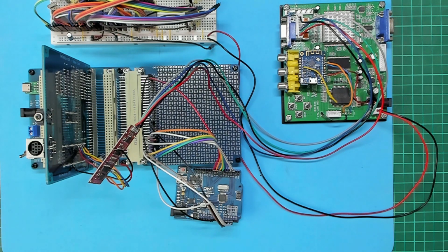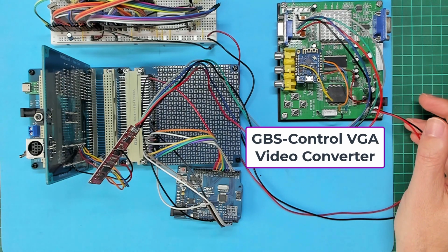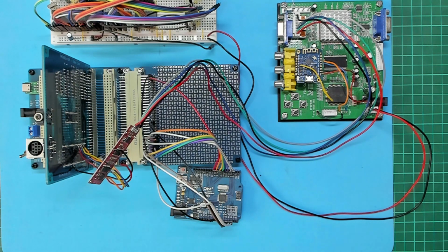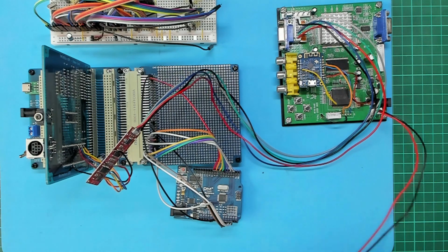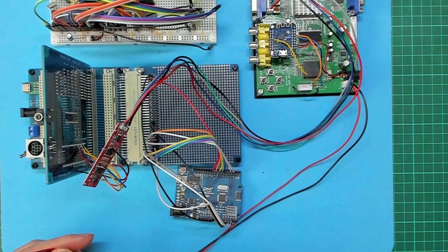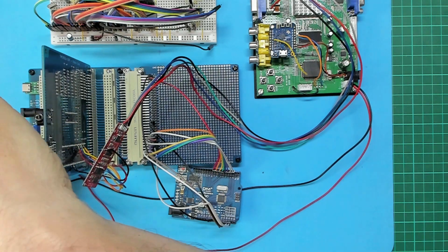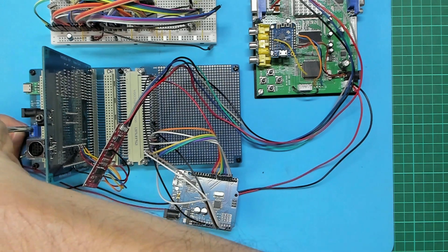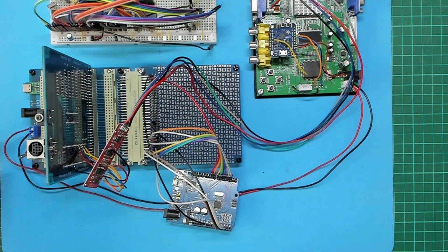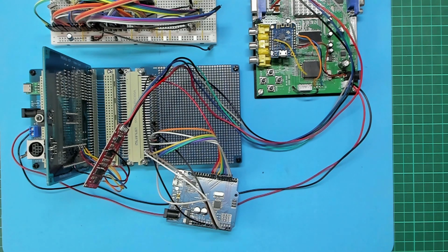Finally, for this test, I'll connect my GBS control VGA converter power input to the spare MECB Backplane screw terminal power connector, which is very convenient. So I'll grab the power out of the breadboard, run those wires over here, and get them connected to the screw terminal. It's ground and 5 volts. Now, because those are spare input connectors, it does mean that the GBS control board won't be switched through the power switch, but that's okay.